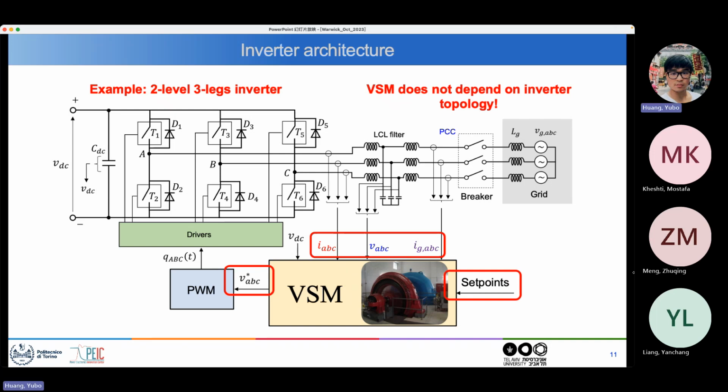But for this reason, to be able to give the pulses of inertia, you need either a big capacitor here, seriously more capacitor than you normally use, or you need to have a battery. Preferably you should have a battery. So that's a hardware modification. It's preferable to have this kind of inverter always next to an energy storage.